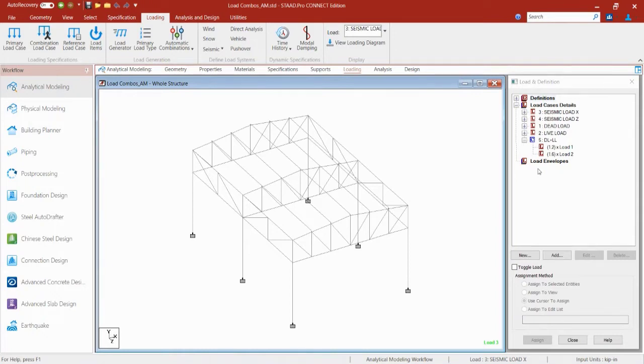Now, I mentioned a few moments ago, how do I know if this is a traditional load combination versus a repeat load case? Perhaps I'm using somebody else's model that they created or started for me. The reason I know this is a traditional load combination is because I see the blue C symbol right here. This means this is a traditional load combination. Let's go ahead and move forward. What I'm going to do is manually create a repeat load case. Now, a repeat load case is, I'm not saying a repeat load combination, it is actually a load case.